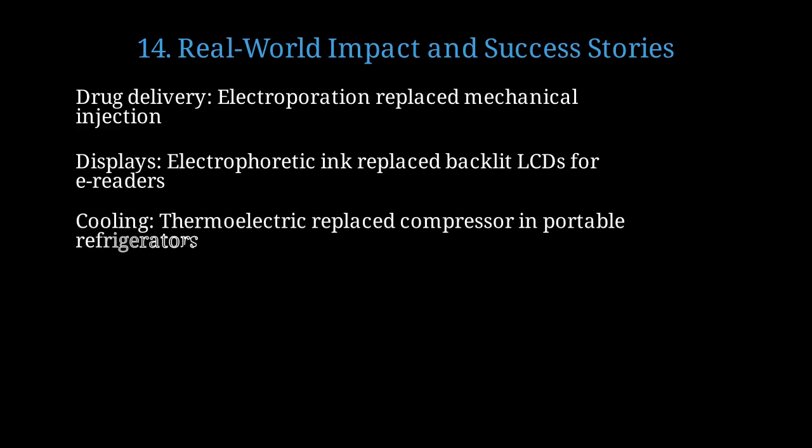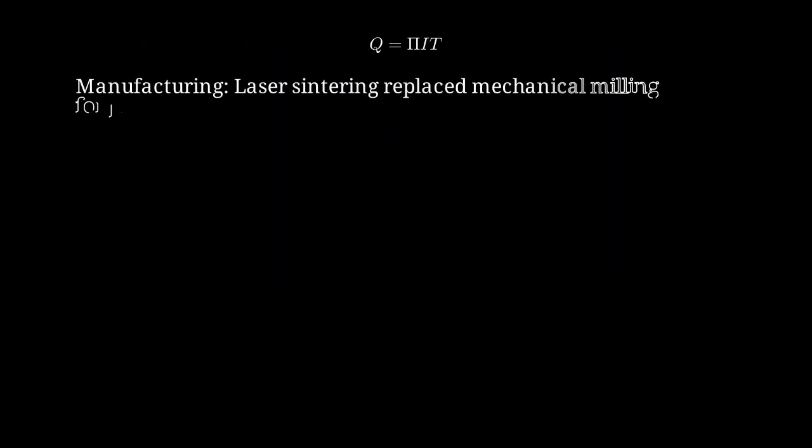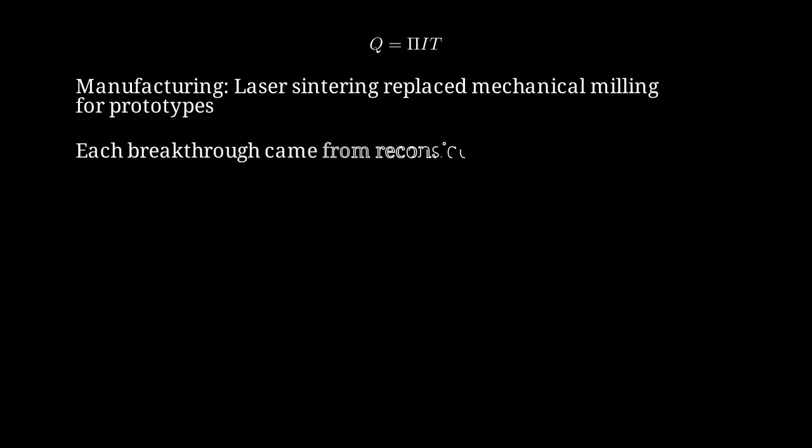Thermoelectric coolers based on the Peltier effect eliminate mechanical compressors in compact refrigeration. Peltier cooling rate equals Peltier coefficient times current times temperature. Selective laser sintering builds parts through thermal fusion, eliminating subtractive machining for rapid prototyping. Each breakthrough emerged from reconsidering fundamental functions without bias toward conventional mechanisms.